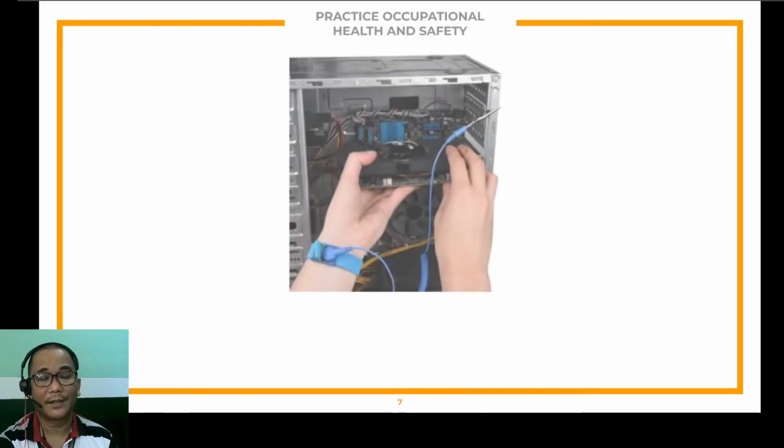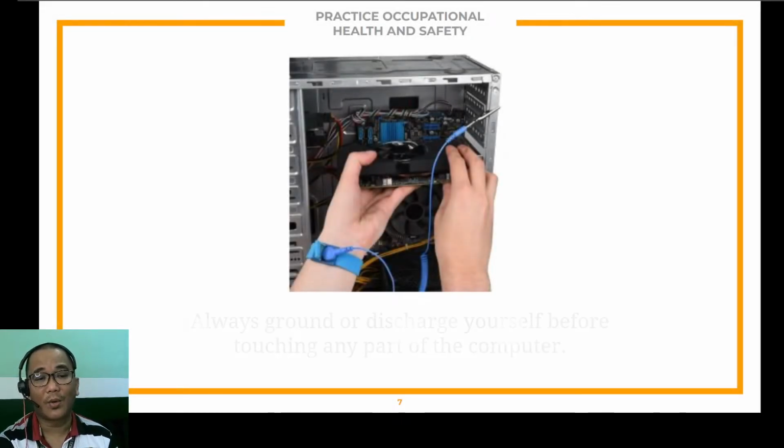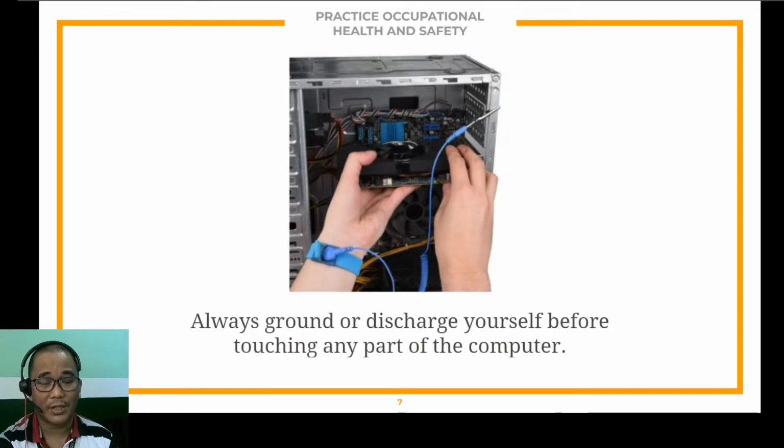The next one, always ground or discharge yourself before touching any part of the computer. So we have a wrist ground strap, which we can buy online.